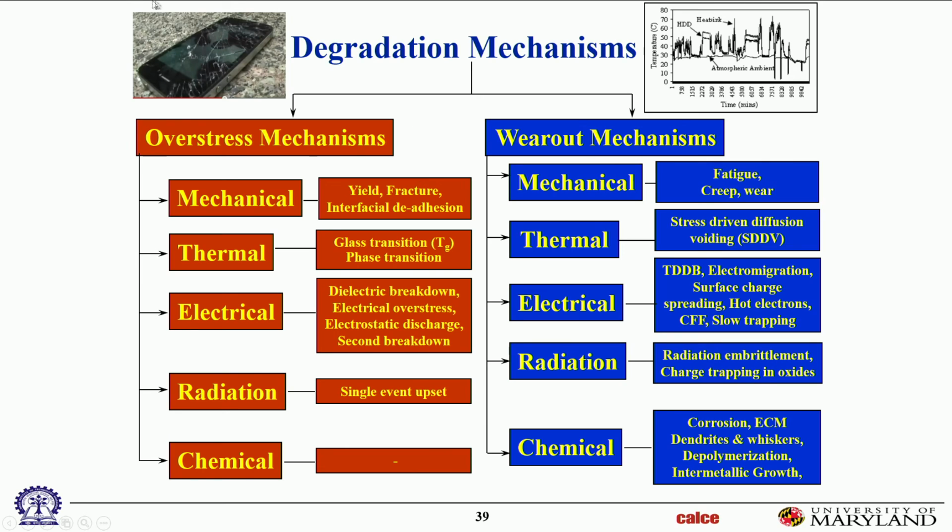And vice versa. I may drop my cell phone and cause a residual stress because of plastic deformation in a connector, and now that connector may no longer last for 3 more years, it may only last 2 more years. That means it now fatigues faster because of that residual stress. So that overstress fall has reduced the fatigue life. So interactions. One more thing, one final thing.